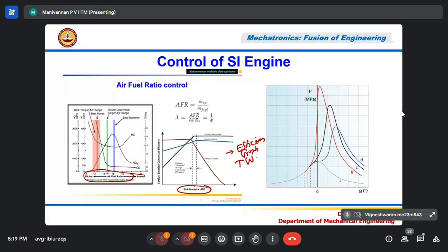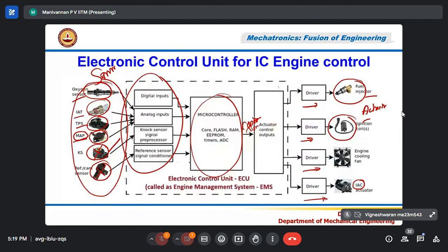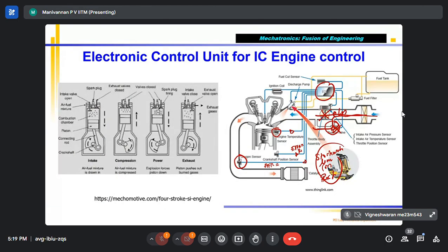the three-way catalytic converter, TWC. I already told you, correct? The three-way catalytic converter will be put inside the exhaust silencer pipe, so the exhaust goes through this. What is its job? Its job is to convert HC, CO, and NOx coming out of the combustion chamber due to improper combustion or misfiring or any other combustion-related cause. If it is produced, that will be converted into CO2 plus H2O. That is the job of the three-way catalytic converter, which is attached to the tail pipe.